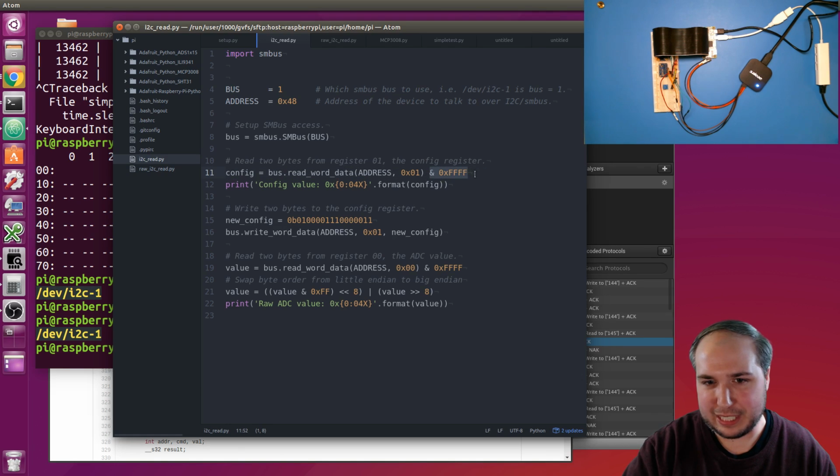I technically don't even really need it here. It's just that I get in the habit, when I'm writing Python code that's talking to devices and doing embedded stuff, of being very explicit and saying, I'm expecting a 16-bit value, so those are the only 16 bits I'm going to care about. I'm just going to mask out everything else. It's smart to do that because you might forget, and then maybe you're reading data you don't expect, higher than a 16-bit value, and things start subtly breaking. So you see this a lot in my code, because this is effectively converting to a 16-bit value.